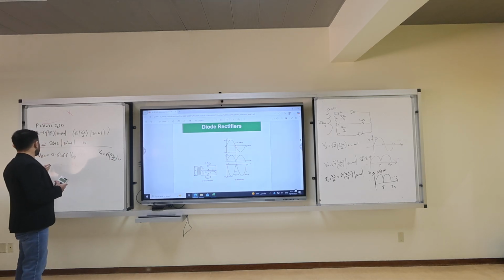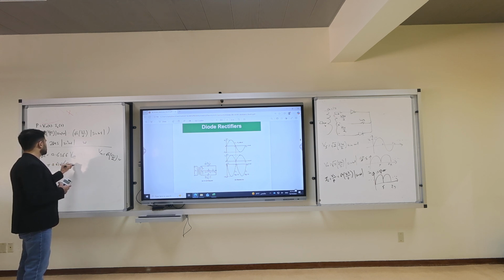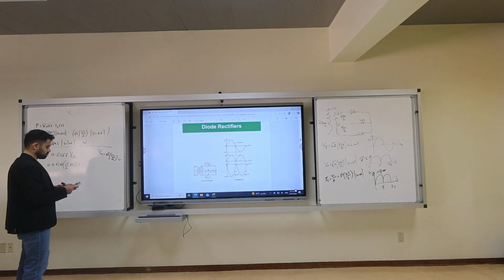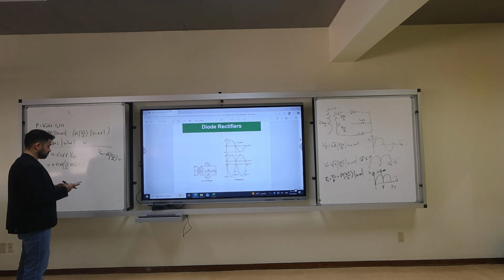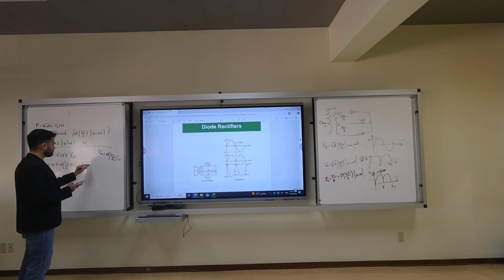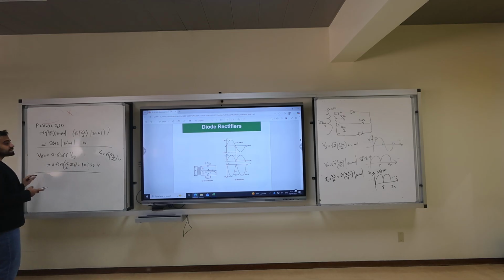So VDC is 0.6366 times square root of 2 times 230 over 2, which was 103.53 volts.